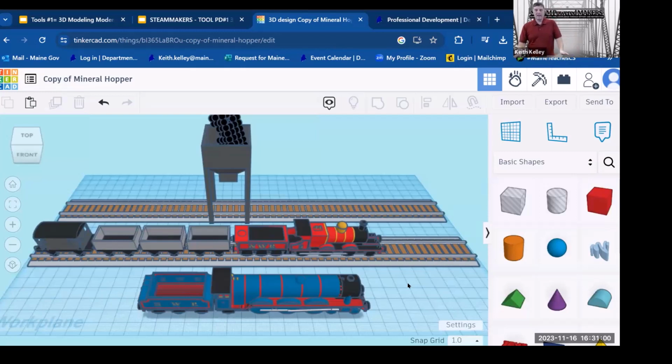It goes from an STL or an OBJ, and it has to become G-code. G-code is slicing. Everything with 3D or a laser is either cutting the layers, subtracting them away, that's your CNC, that's your laser, burning it away or cutting it away, or it's adding to it, stacking the layers. So it has to have something that can slice all the layers.